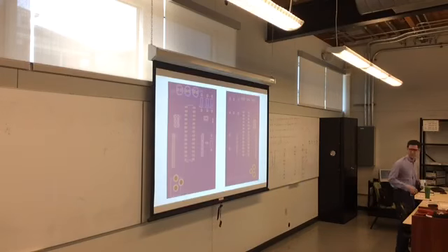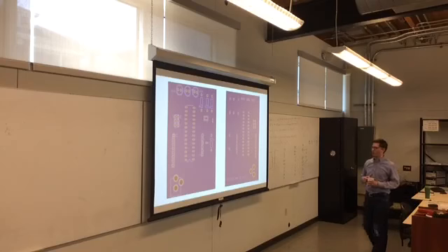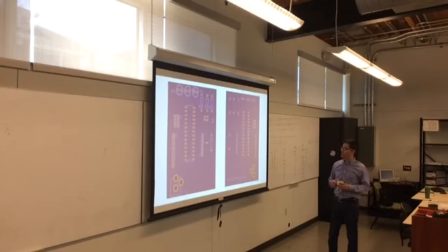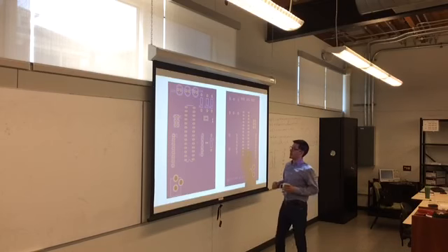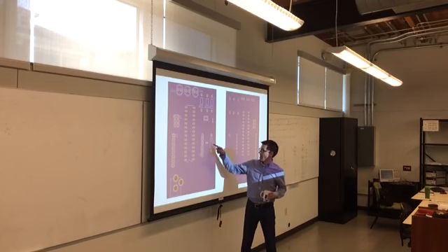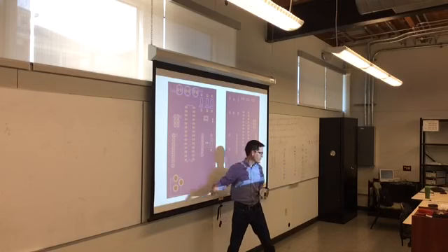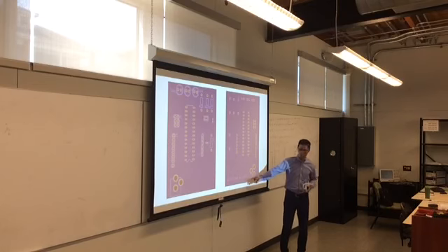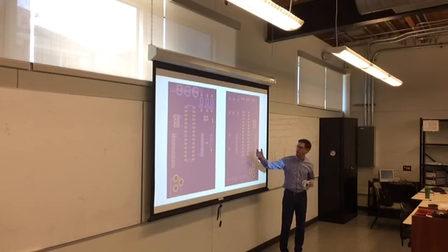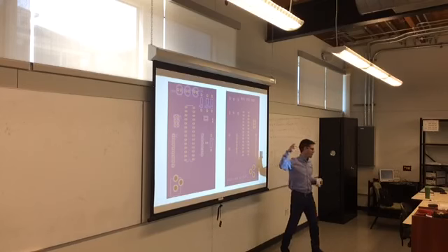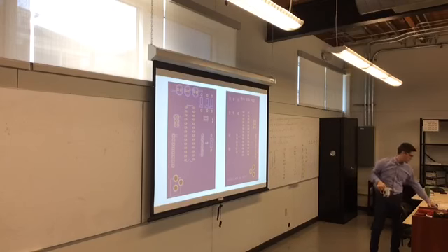So the stuff you get back looks like this. It's kind of nice. This is one of the through-hole designs. You can see where a couple students, this is from last year, not this year, have labeled their resistors so they know which ones go where. They've also put a nice little note on the bottom that says this is the bottom, so they don't forget. Because this student did through-hole design, it doesn't really matter whether your chip gets soldered in here or here, except it will be completely inverted. And all of your things will be flipped and disconnected.